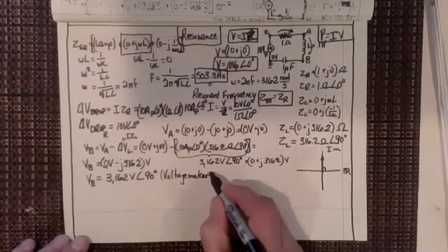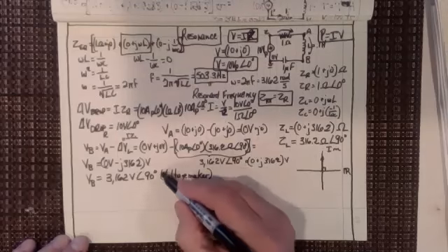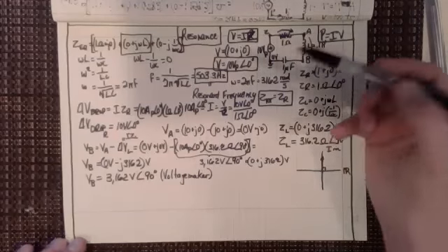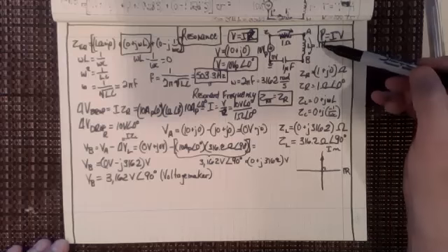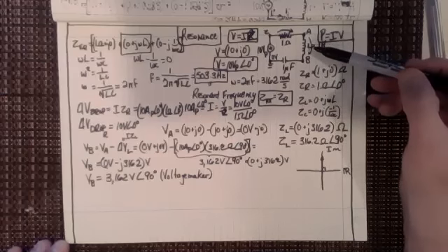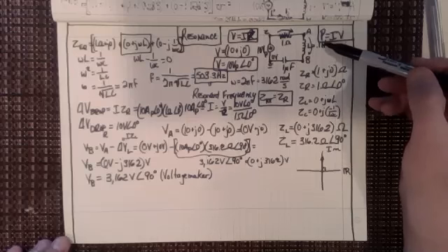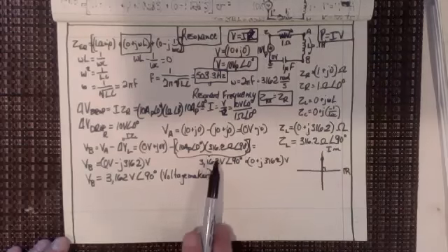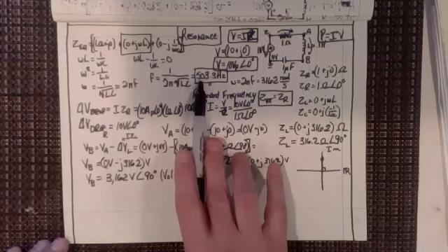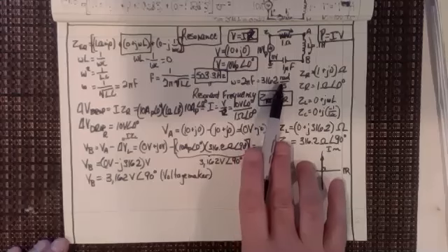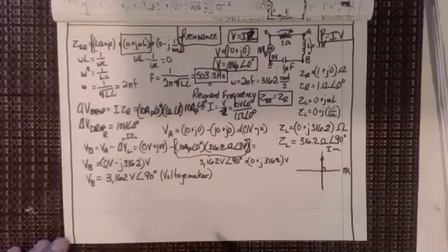circuit, right? And what do you want to do when you're making this voltage maker circuit? Well, you want to get the current as high as possible. And of course, I did that by reducing the resistance to as low a value as I can. And then you also want to get this over here. Now you can see that if I'm using a 0.1 Henry thing, that brings it up to this, right? Because I'm using it still at the 503 hertz or 3162 radians per second.